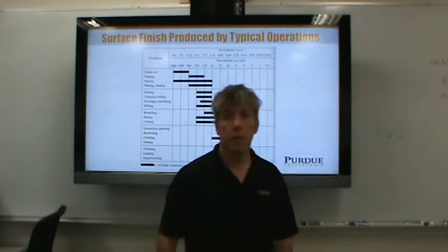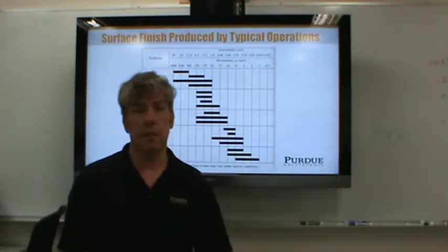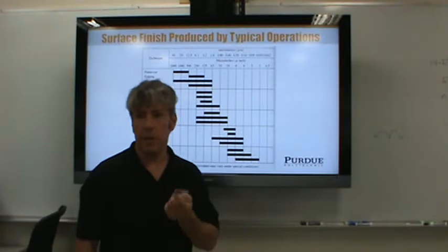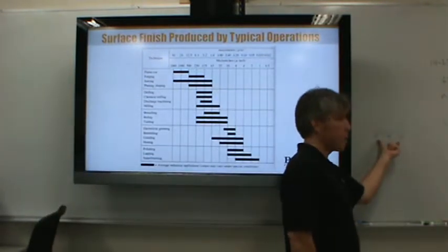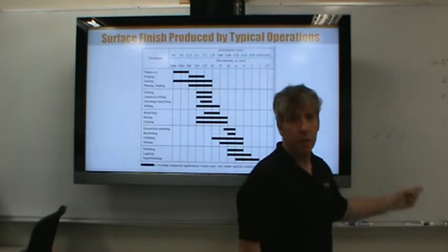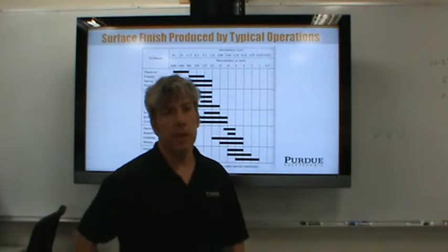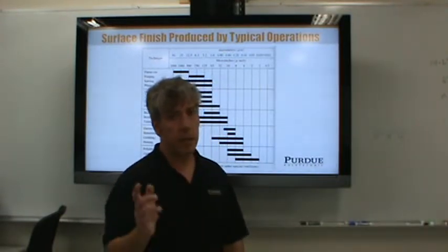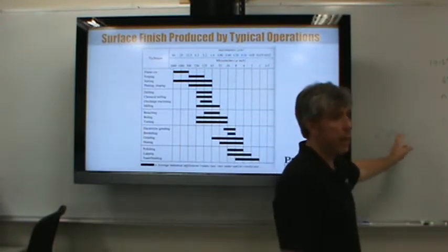Yes, sir? Is that kind of like the bottom plate on a stapler, sort of? It is, yeah, excellent example, never thought of that. You're right, it's a lot like that. But since I was dealing with a part that was only a 32nd of an inch, this was a tiny feature, right? And asking the machine shop to make that was not really practical. So we had a local company we contracted out to, and I had them EDM this, in fact, wire EDM.